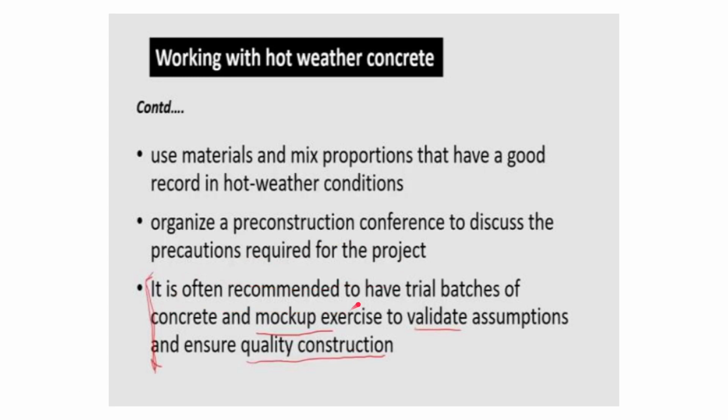It is often recommended to have trial batches of concrete and a mock-up exercise to validate assumptions and ensure quality construction. So we need to perform some mock testing, mock concreting, and all those, so that our assumptions are valid and the quality control is established.